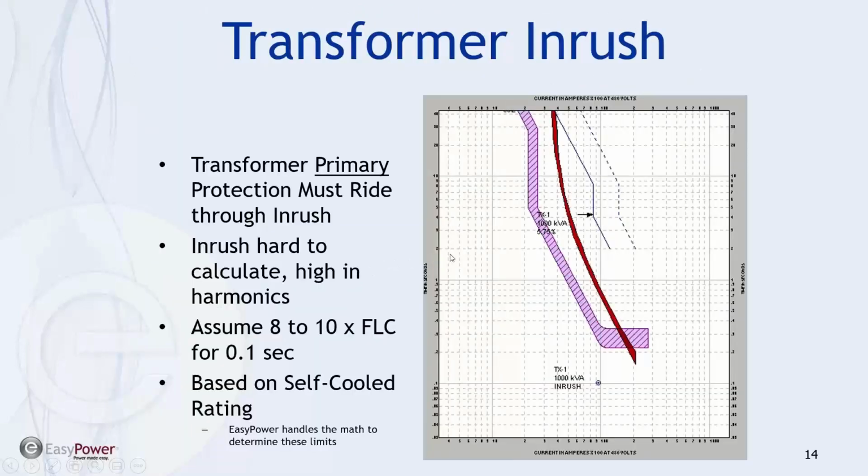And I think getting to Chuck's point, when we plot the transformer damage curves, again, the 100% damage curve is the dotted line, and the derated or 58% single phase to ground plot is the solid line, because the single line to ground can be a phase overcurrent.